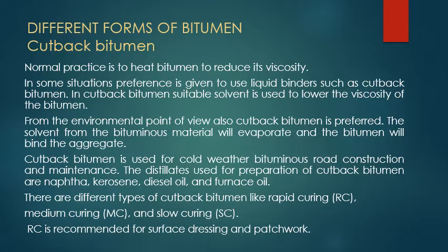The solvent from the bituminous material will evaporate and the bitumen will bind with the aggregates. It's a simple concept. And this cutback bitumen is used in cold weather bituminous road construction in cold countries, and its maintenance.